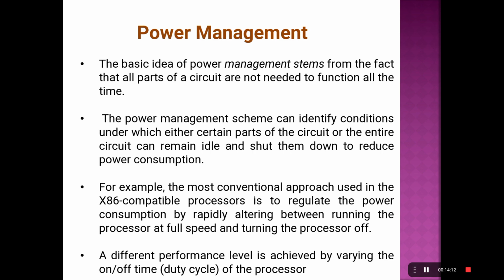Therefore, obviously, we can save power, because if you are not applying any power to a particular device, no static power dissipation will take place, right? That is the basic criterion. Whenever the device is in the on condition, only then will static power dissipation take place. If you are not providing power to the component, there is no chance of power dissipation in static mode, which we can also call the sleep mode or the low power mode. That is the basic idea behind power management.